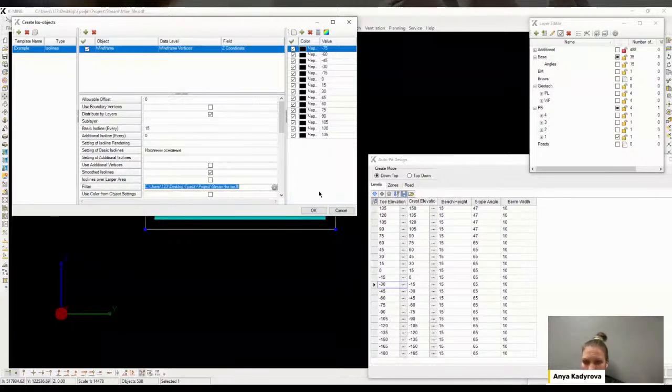So now we will just demonstrate how the automatic design model works in KMI using the example of creating several pushbacks that were obtained from the Pit Optimizer model. The model allows you to build both top-down and bottom-up. So for the first pushback, as well as for building of the final contour from scratch, it is proposed to use the bottom-up construction method. And in order to define guidelines, it's necessary to create them as lines, which is possible using the standard KMI functionality.